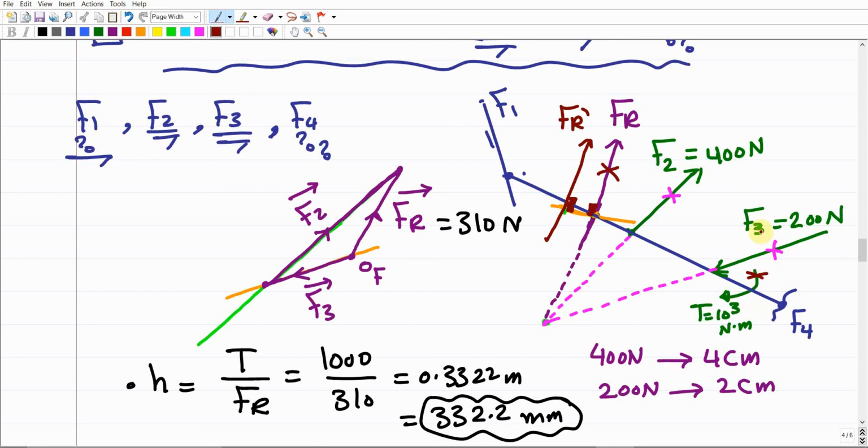So now we combine all of the forces that were located in the middle into one force. Even the torque is combined into just one force. So now we end up with a member with three forces. This is the three force member that we explained before: one force in the middle, one force at this end, and another force at this end. Now the objective is just to find these three unknowns.